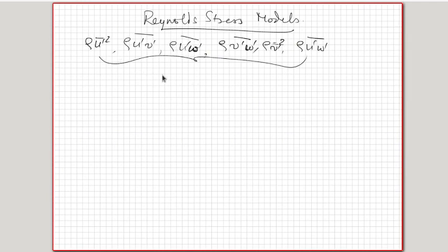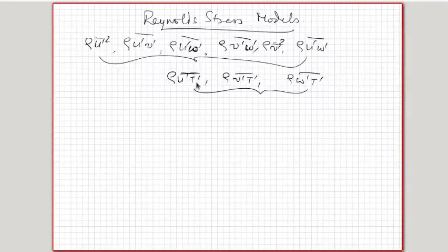And if I have energy equation also, then I'll have a rho u prime t prime bar. Okay, then you have a rho v prime t prime bar and a rho w prime t prime bar. Okay, so 3 different turbulent diffusion of energy terms.